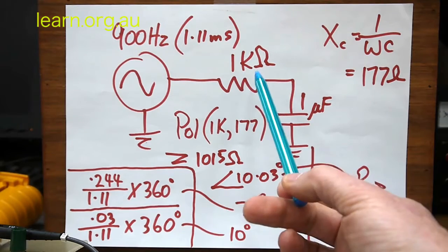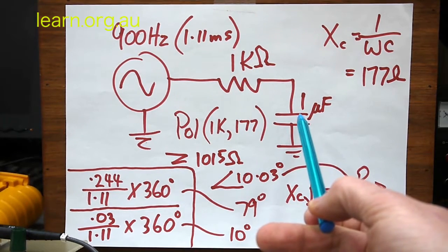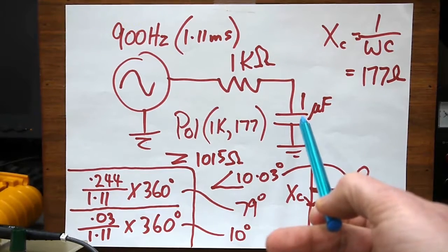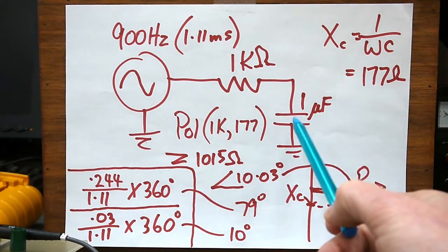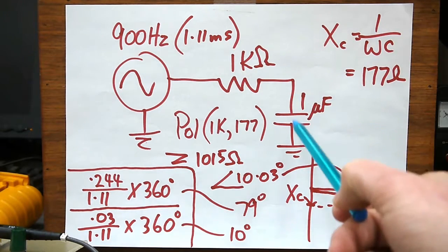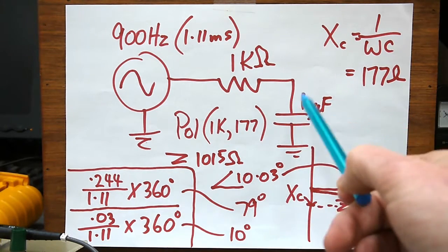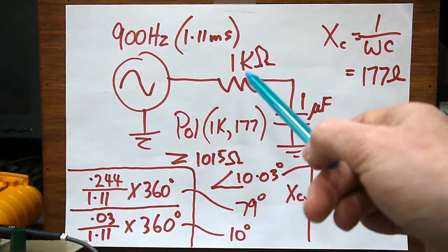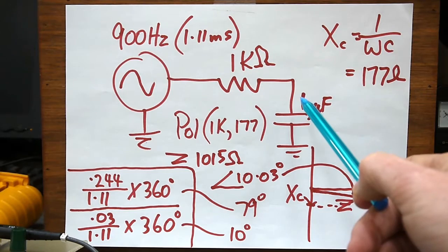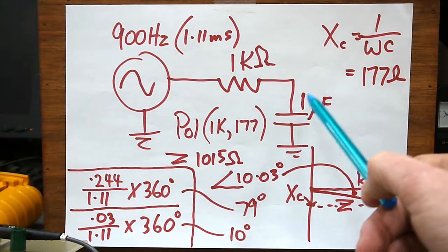Series circuit with 1 k-ohm resistance, 1 microfarad of capacitance. And at one point we have to transpose these components in the circuit so that we have, to start with, the capacitor in shunt, and then later the resistor in shunt with the output, so that we can measure VC, or when we move the resistor to the output, we can measure VR.